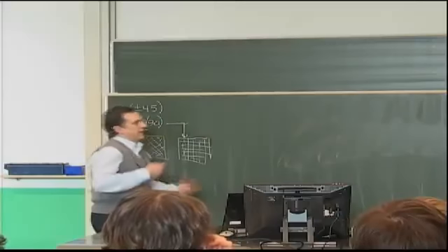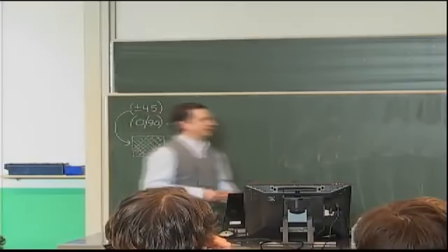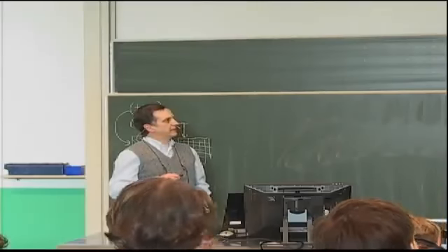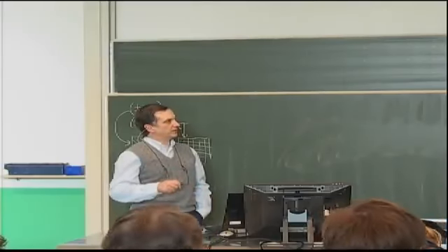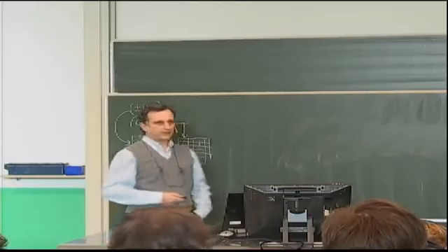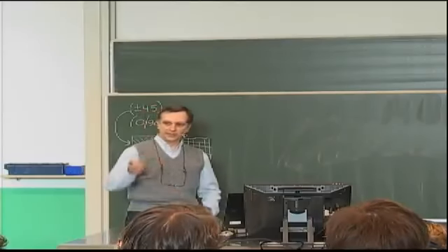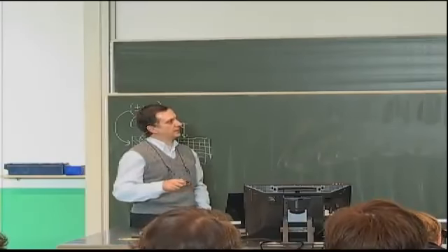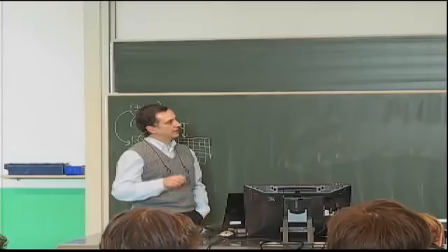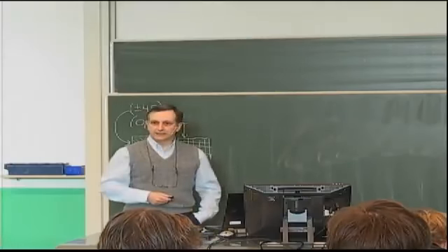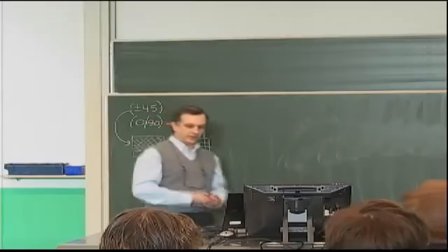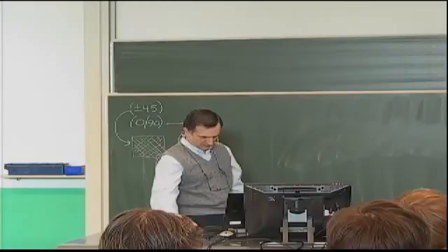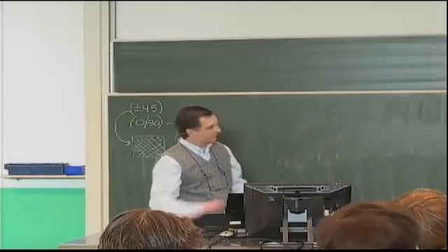And the theorems say, this is one way of stating them, that in the first case, if you want to satisfy all the governing equations, you have to pick. Some of them you will satisfy exactly, and some of them you satisfy approximately. If you choose to satisfy exactly your strain compatibility, and strain compatibility means this equation here.